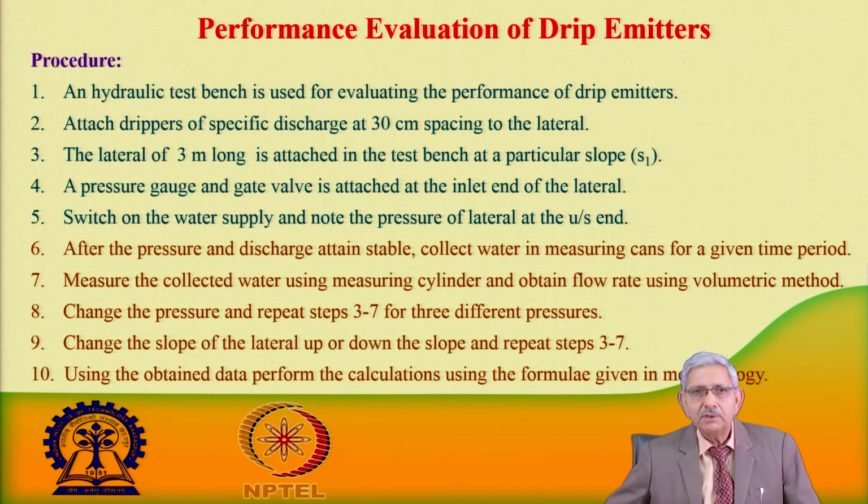I am going to present here the performance evaluation of drip emitters, when the drip emitters are being manufactured. So, as I told you, randomly from the lot the samples are collected, and these samples could be of the order of 10 to 25 in number, and then by using a test bench their performance is evaluated.